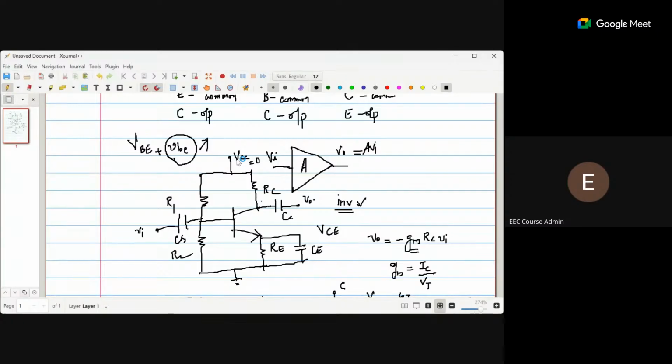The analysis, the function of the circuit, everything is the same. You Thevenize and find all those things; that is the same. So understand what DC analysis and AC analysis are. These bias resistors, collector resistance and emitter resistance, all these four resistors are needed for setting the DC voltage and DC current. What are this DC voltage and DC current we are talking about? VCE and IC.